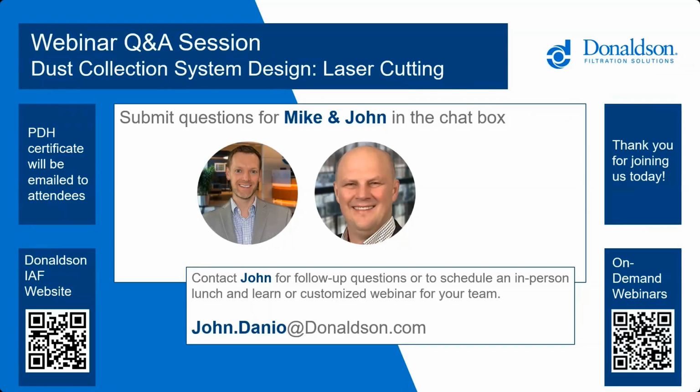And then also make sure their dust is tested, right? So you know exactly what you're dealing with. Yep, that's the best way to go about doing that. And then what were you going to say, Mike? Sorry, I didn't mean to interrupt you. Oh no, you're fine. And then obviously mixing metals, which was mentioned in this presentation as well. That's something that also can cause explosivity depending on what the metals are. So once again, something to consult with your local AHJ.